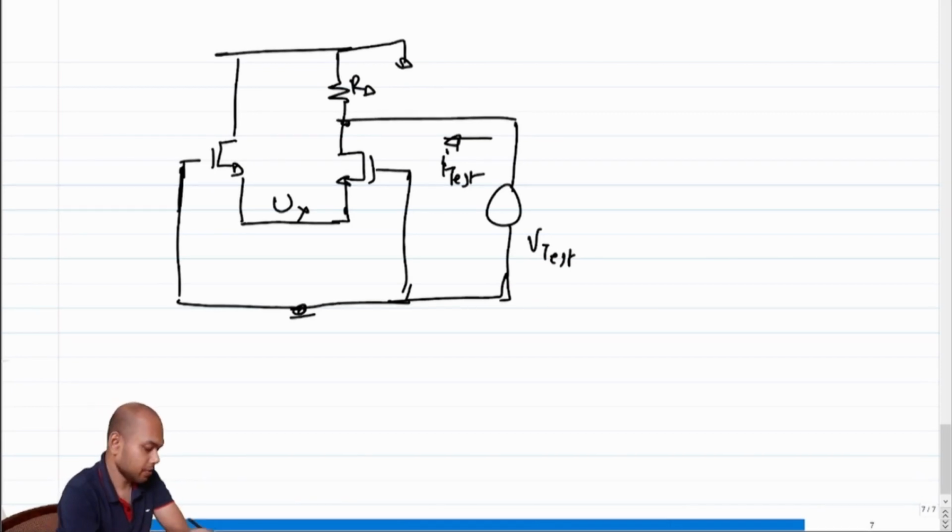The gates are shorted to ground, right? Which means that there cannot be any current, because there is no way the source voltage can be excited, because nothing can flow from top to bottom, right? So this is equivalent to saying that no current flows here, so this guy doesn't exist, right?